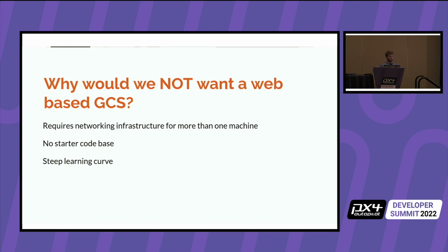Well, if you wanted something that simply lives on an Android tablet, a web-based GCS is going to be pretty heavyweight. It works well as a viewer, but it doesn't work well to run the web-based application itself. There's not a great starter code base. I'll say when I first jumped into doing web-based GCSs, the example I started with was the MAVSDK JavaScript example, but there's inherent problems with that.